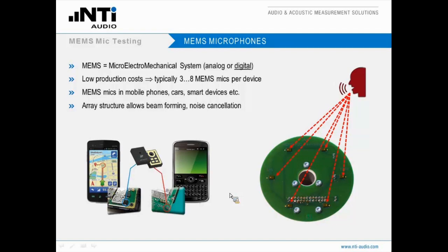One more side information to which I will come back later is that a prerequisite of this procedure, of this technology of beamforming, is that these MEMS microphones on the array are behaving very similarly. So each of these microphones should have a comparable, a similar sensitivity so that it translates the incoming sound in almost the same way as the neighboring microphones. But as stated before, I will come back to this issue later.